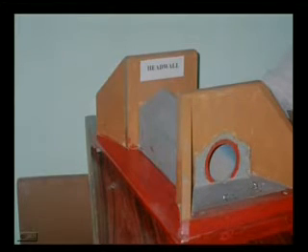What does this apron do? It prevents the bed from getting eroded. This is a thick layer of stone masonry here. This is provided in order to safeguard the bed here from the gushing waters which are coming out of the mouth of the pipe culvert on the downstream side. A similar apron is also provided on the upstream side.